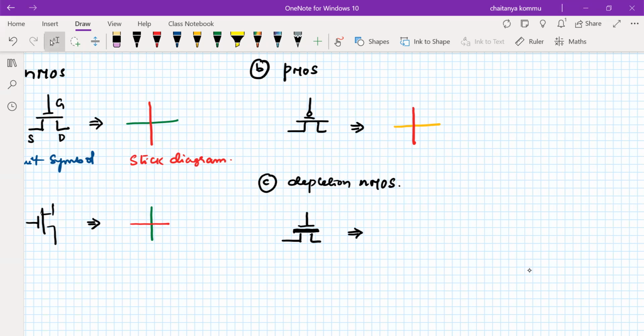So in this sense, it is an NMOS transistor. Therefore, diffusion is green color. Polysilicon is also there, and the polysilicon is red color. Now here, we want to mention the implantation.